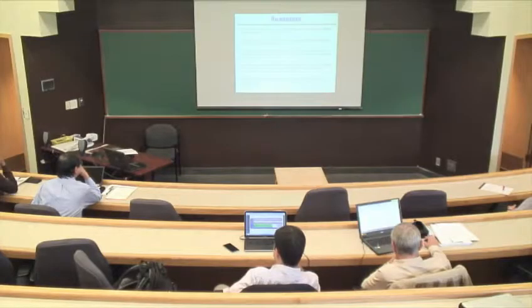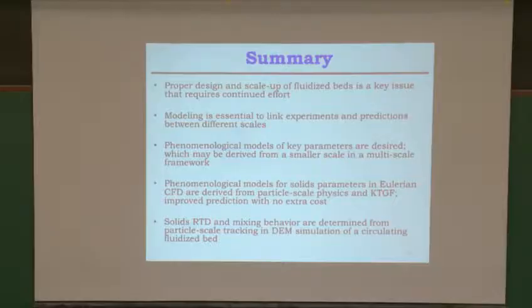Now, in order to develop closure laws, we need to work on the physics of how particles interact. In the model that I showed you, I didn't account, for example, for torque and also dissipation energy. So the next level would be to deal with how energy dissipates because the particle is spinning, and one would obviously have to do a torque balance in that case, a balance of angular momentum. That would increase the complexity significantly. That's really what's necessary to take it to the next level.